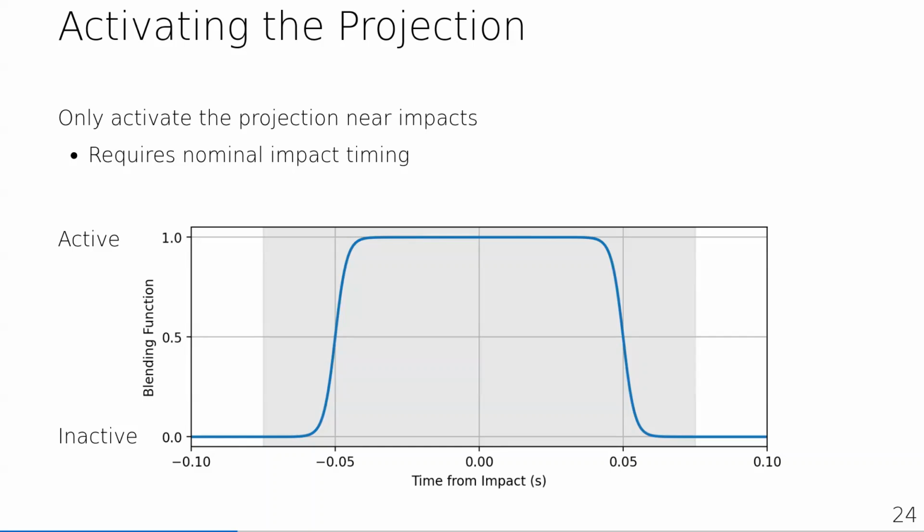So you did not use here the OSC projection of the impact invariant space for calculation, right? Is there a particular reason, like the impact force is small enough, or it's not necessary? Yeah, so we could have, we didn't, just because it ended up not being necessary. I think the discontinuity that we're scared of in jumping comes from much larger impact forces than from touching a tray. But you could use this. Actually, the very initial inspiration for this task was trying to combine impact invariance for picking up a heavy object really quickly. So that was part of the consideration, but in practice it wasn't necessary, so we didn't do it.